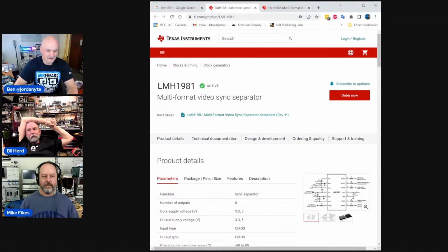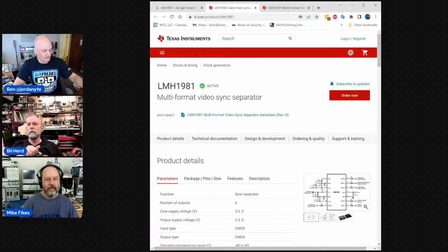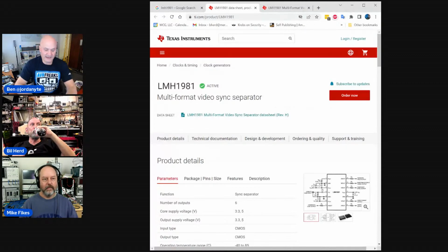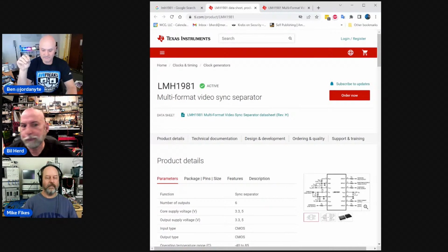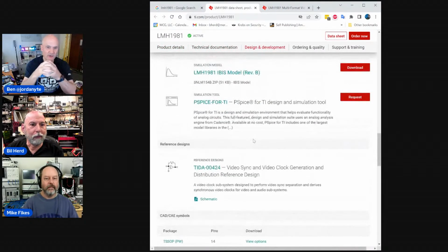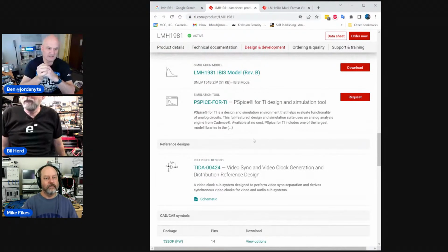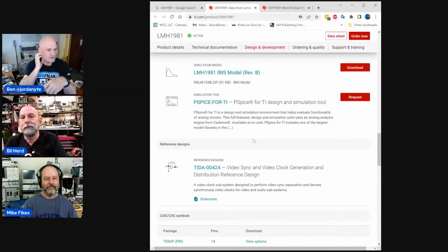When it goes into digital, is it doing like just discrete event simulation type stuff where it doesn't care about the actual physical voltage levels anymore? It does actually mix both. The simulation engine that used to be in Altium Designer was called XSpice from Georgia Tech, and it was doing the same thing. And it had a C-like programming language for defining the logic at the core, but around that it would actually model different voltages and things. It wasn't just ones and zeros. It would actually interact.